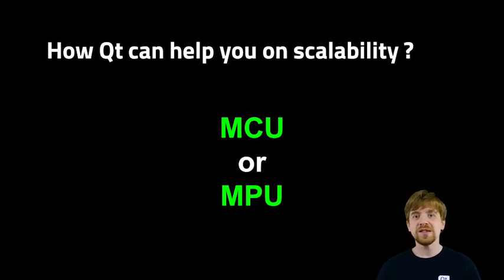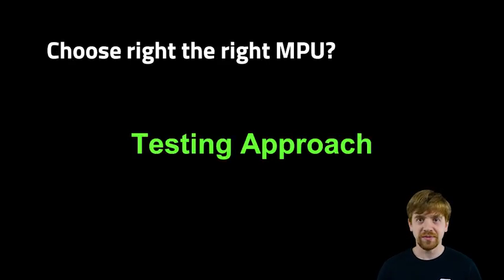The thing is, if we want to try it, let's say I have done my range and I want to try 1, 2 or 3 MPUs. I have selected them. And now what do I need to do? First, I will need an operating system to put on it, because Qt on an MPU platform does not support bare metal, it supports only running on top of an operating system. And you have the full Qt capabilities on top of operating systems.